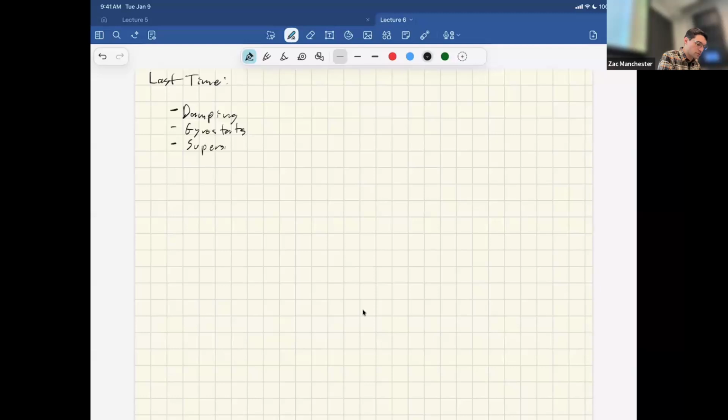So this is super spin, which is basically augmenting the effective inertia about a non-major axis to make it stable using wheel momentum. And then we talked about dynamic balance, which is effectively canceling out nutation about a non-principal axis. So with these two things, we can make a spacecraft spin stably about any arbitrary axis we want. And I think it's worth pointing out these are not control laws. This is open loop, right? These are just constants we're putting into the wheel speeds that are reshaping the dynamics in an open loop kind of way, which is a cool thing.